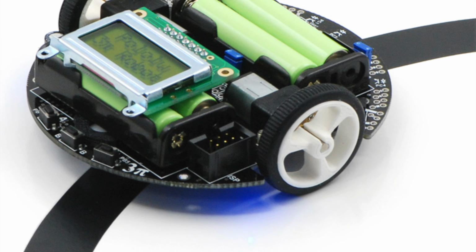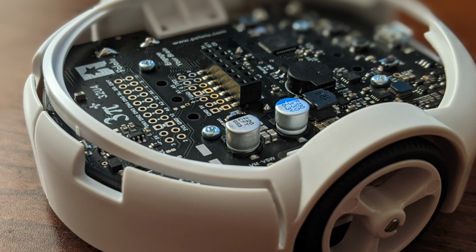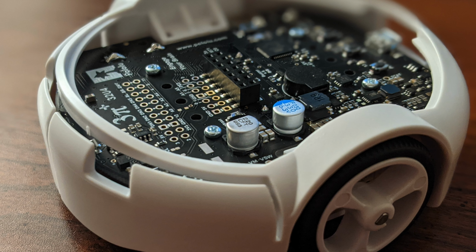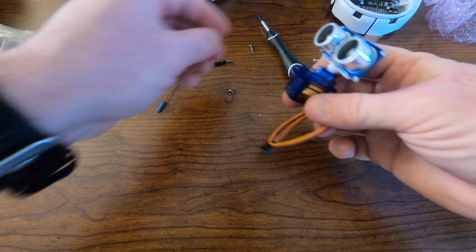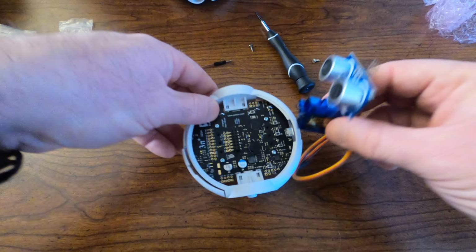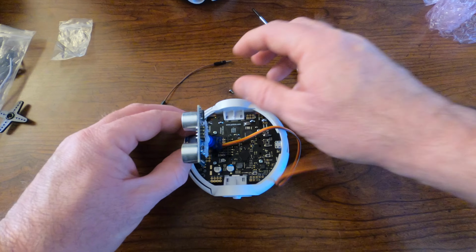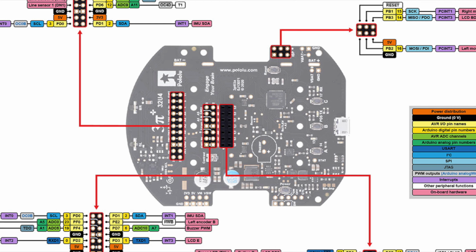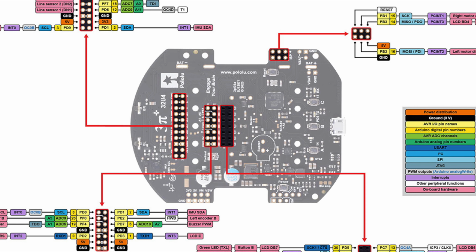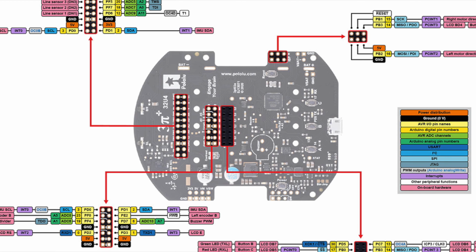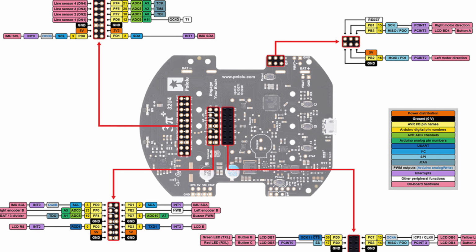There are a few more features here worth mentioning, such as the line following sensors, but what I really want to drill into now is the expansion ports that are available to us on this robot, since we're going to need range finding sensors such as the ultrasonic ones that we discussed, and ideally I want to set this robot up with a small servo and an ultrasonic sensor. Now the expansion ports that are available to us do allow you to get to pretty much every pin that is available on the Arduino Leonardo compatible 32U4 microprocessor.